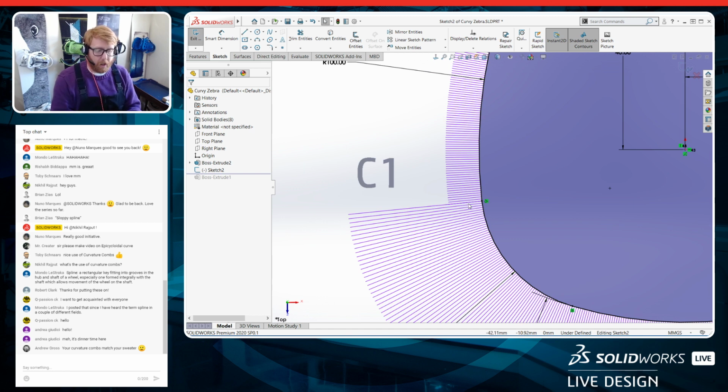And why does that matter? If you were doing a low gloss plastic with maybe a texture on it, it probably wouldn't matter. You wouldn't see it. Or if this is the inside and you're trying to mill out a pocket, who cares? Do a tangent. It makes it super simple for the person doing the machining. You can just use a ball end mill bit and put it in there, no problem.